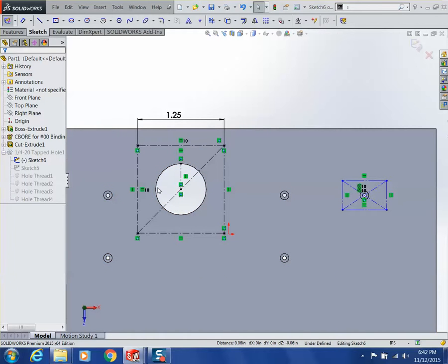You can also possibly use a block for that. Sketch block? Yeah. I suppose I haven't thought about doing that either. Yeah, you can grab a sketch block and be able to drop those back in with a set pattern. You'd have to have a point to lock it down back to something else, but I'm assuming everybody's fairly familiar with what a sketch block is. You'd get this all set up with one or two points and lock it down, and you could drag those in from a library too. All that kind of stuff will work. That's one of the cool things about the SolidWorks Hole Wizard, it's driven from a sketch this way, so there's a lot of things you can do sketch-wise between blocks and macros and pulling things out of a feature library to speed this up a whole lot if you run into it.